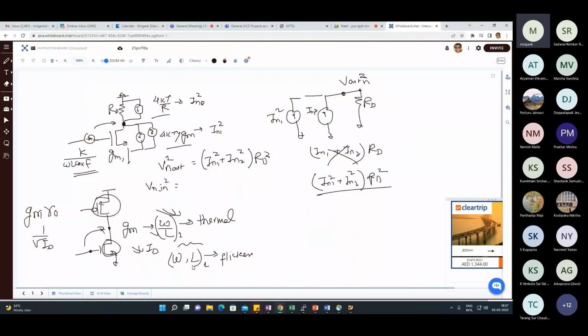So when we are talking about the speed limitation or the bandwidth limitation, analyzing poles in the open loop response is sufficient, at least for the bandwidth that you can get from the open loop amplifier, which you can analyze entirely by poles. So zeros become more important for closed loop analysis. For that, of course, you should first know where the path of the zero is, which points will give you a zero, and then in the exact analysis you can see, once you do the closed loop analysis, how those zeros will be changing. Those things we will discuss. When we discuss the closed loop frequency response, we will look at the effect of zeros.